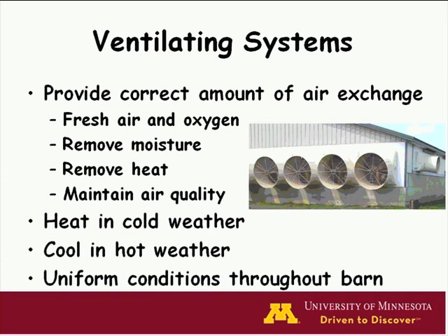We expect a lot of our ventilating systems. They need to provide this air exchange, bring in fresh air and oxygen for the animals, and then they remove moisture and heat and a number of air contaminants that are generated inside the building and then maintain air quality in there. The systems, which has gone a little bit beyond just ventilation, often include heaters that add heat in cold climates and cold weather, and especially for young animals and poults.